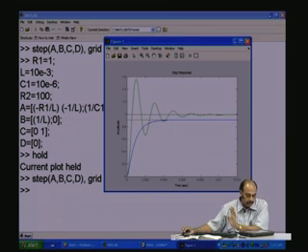The moment we change the parameter R2, you are having overshoots beyond 1, and then gradually it is damping to 0. It rises quickly, but shoots beyond the value 1, and then you have damped frequency of oscillation as shown here. Now, what is causing this? From the time domain, it may not be so very evident. Probably we may have to look at the frequency domain and the pole zero domain. The pole zero domain will give a very interesting result.